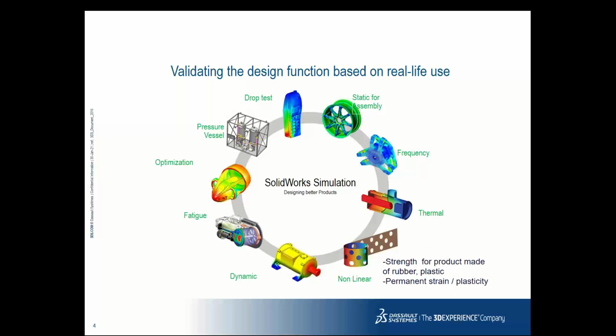So this is the nonlinear analysis. We'll be seeing this in tomorrow's session. Basically, nonlinear deals with the scenarios where your strength is going beyond the yield point. What exactly happens is when the stresses in the model go beyond the yield point, there is a possibility of permanent deformation, or we call it plastic deformation.